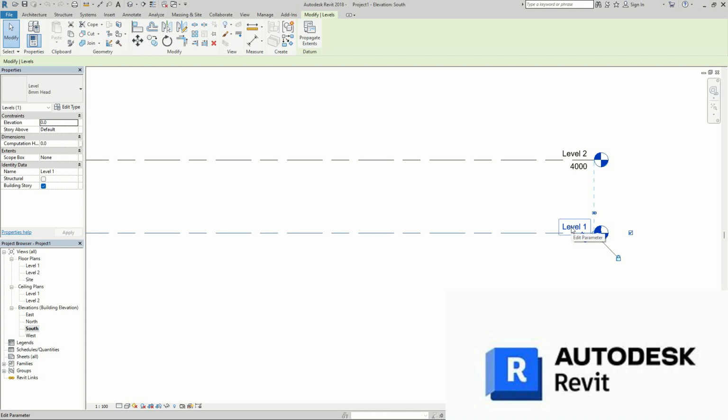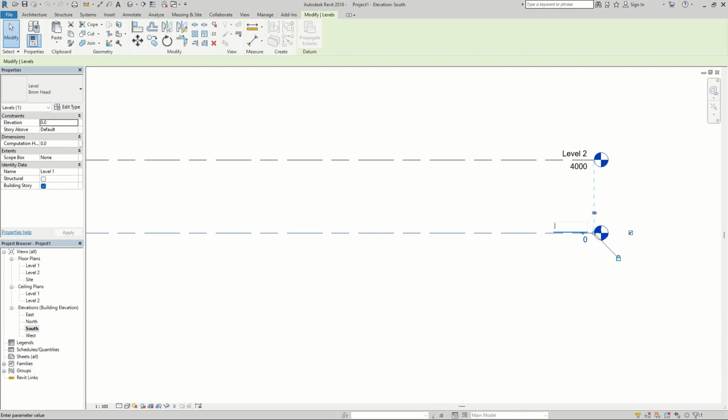So let me click on this, and it shows this way just on your keyboard, or you can click this GL. You can say 1 GL, so you can go serially in your floor plans detail naming system. So immediately I change this level 1 GL, this level 1 will change.